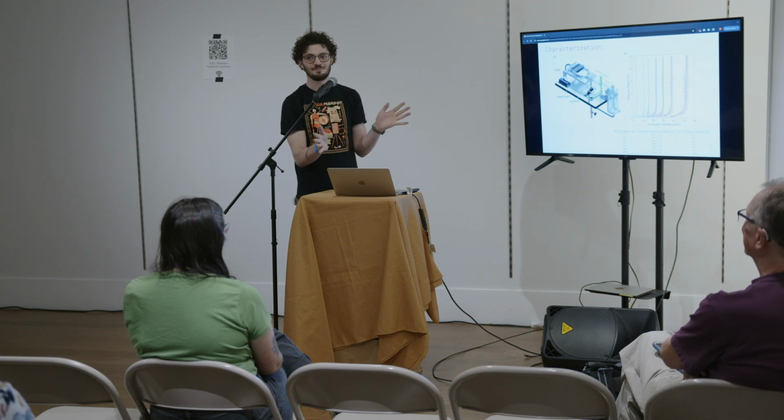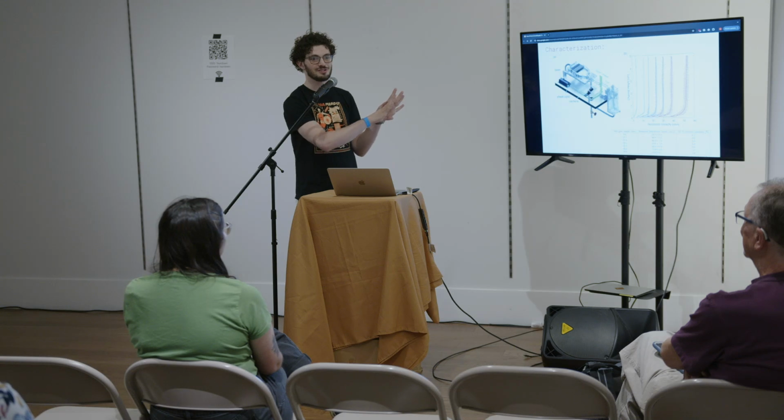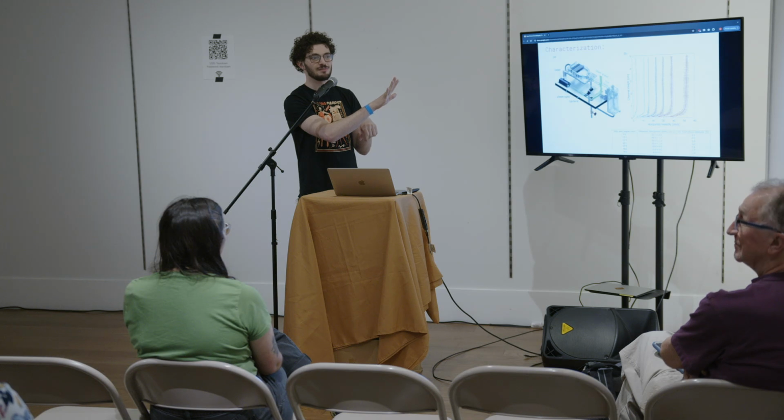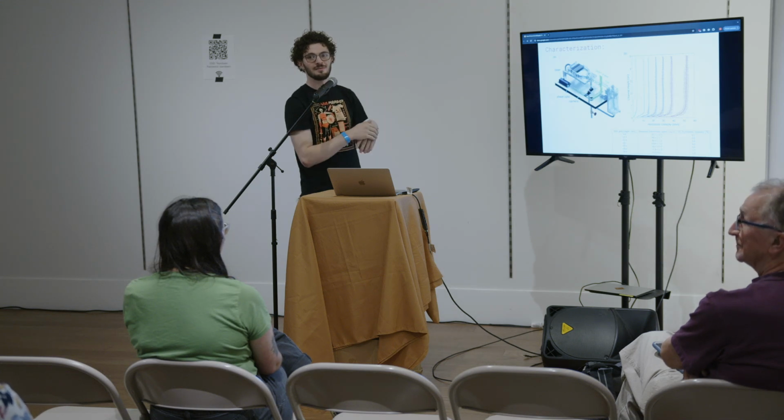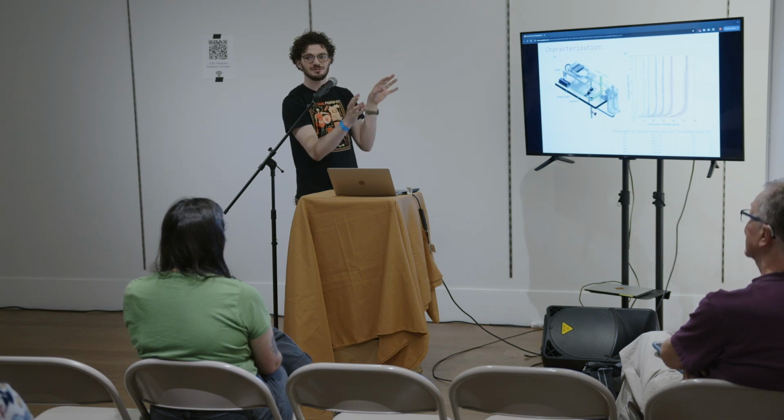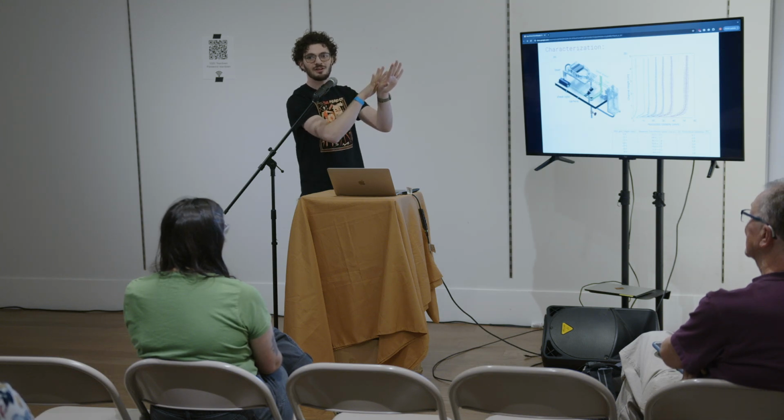And that's the technique of PIV: you watch the particles move, and when you compare one image of the particles to the next image, you can match different areas of the image. For the best match, you then draw a vector from where you started to where you ended up. You do that at a bunch of different grid squares. You can tune things like the size of the grid or how far you look, and you end up with the vector field of the flow.